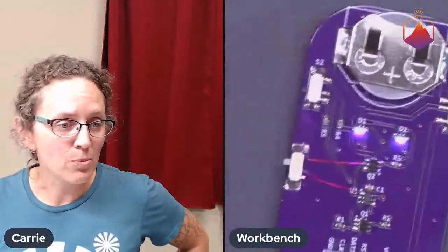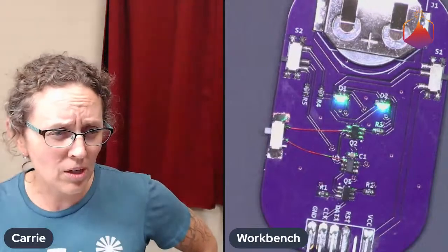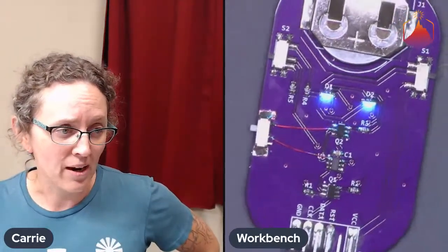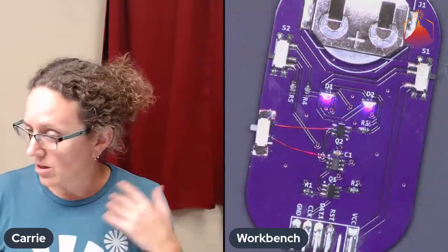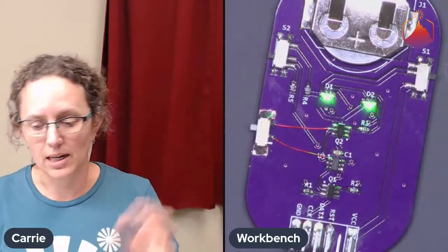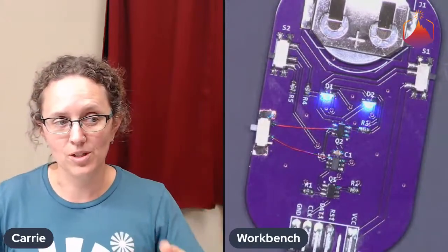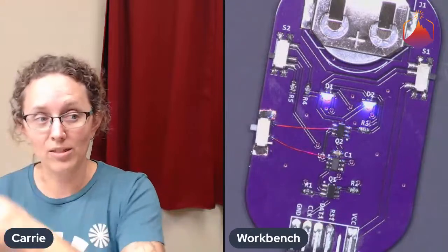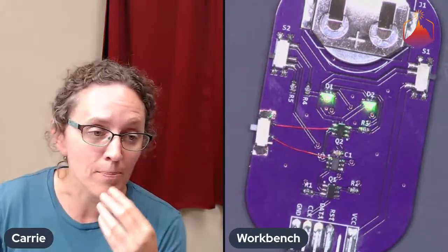So what else is going on with this board? So this board has some bodge wires, because this is the first rev. So this board is powered. They're normal RGB LEDs. They're not the addressable kind. I can't just tell them to be a color. You actually have to give the right voltage on the red, the green, and the blue lines in order to mix them and create the color that you want.